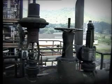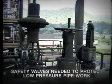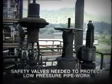Where reducing stations are installed, it is important that one or more safety valves be located downstream to protect the low-pressure pipework in the event that the pressure-reducing valve fails and exposes this piping to the high-pressure steam directly.